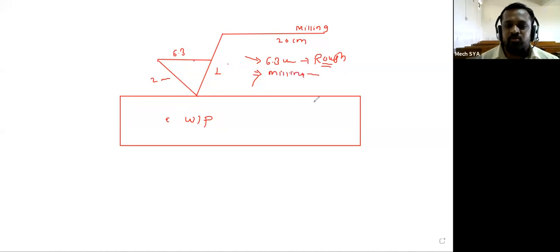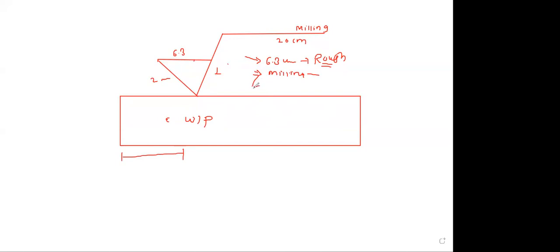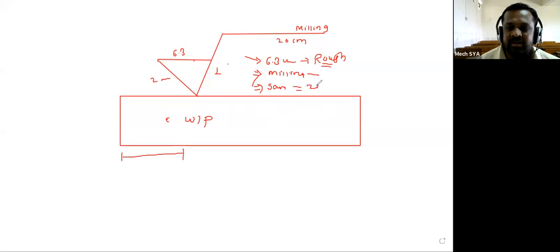And suppose we have to manufacture this component, how much length do we have to take for sampling? How much length for testing? They have given 20. How much sampling length do we have to take here? 20 centimeter. From this symbol you have to understand. Again, during the manufacturing of this component, you have to remember your direction of lay, or we can say the pattern of irregularity.